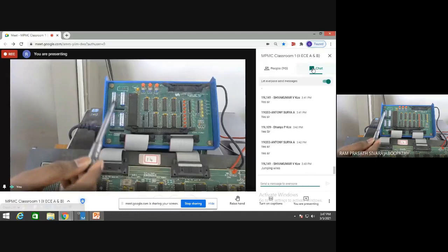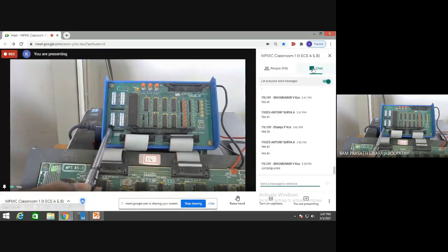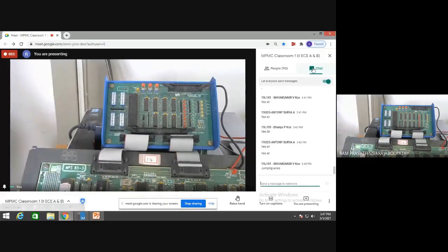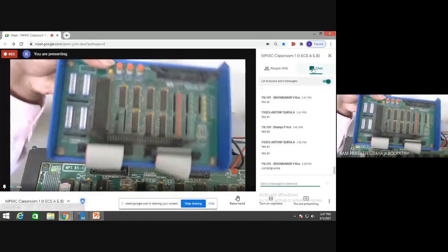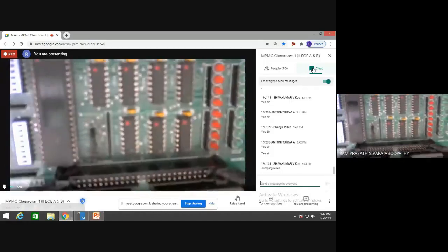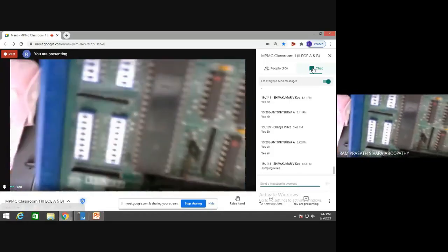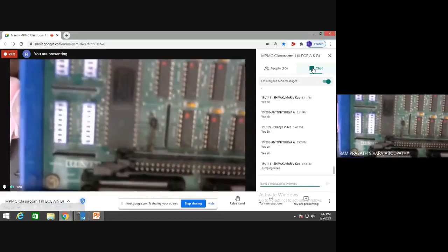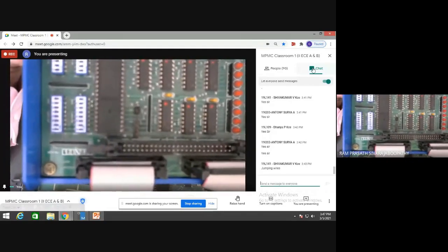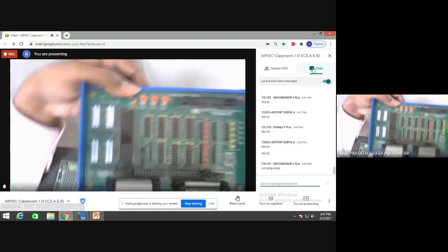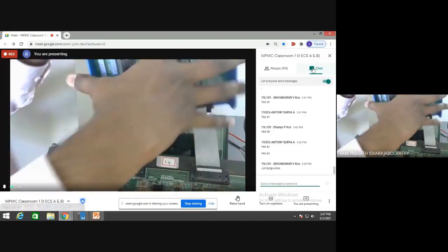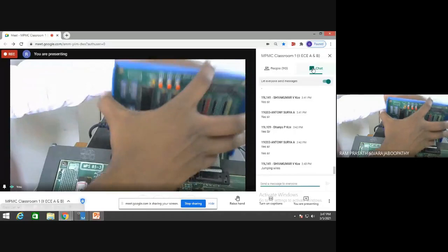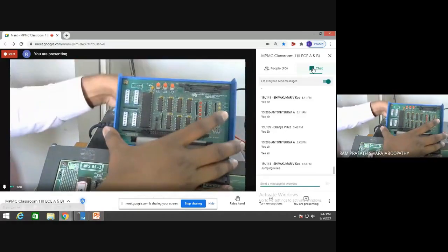I push all the switches to the IP side on top, setting input. For the lower switch, to configure port B as output, I am going to put all the switches in the OP position. You can see. I think you can see as much as possible. It is not clearly visible. IP OP is written there. Fine, don't worry about this. When you come to the college, you can see it clearly.